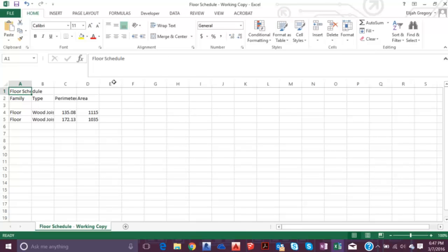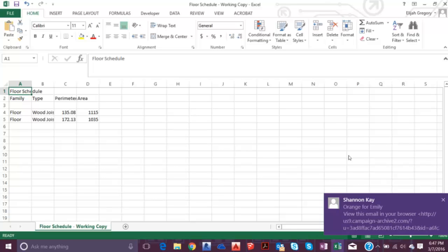Depending on the level of detail you're seeking and the estimating policies of your company or whatever estimating you're trying to do, you can derive these quantities in various ways. I personally suggest the parts, but if you want to go ahead and use just the family and the type and then plug that into formulas that you have in different estimating software, you can go ahead and do that. But that's what we have for today.